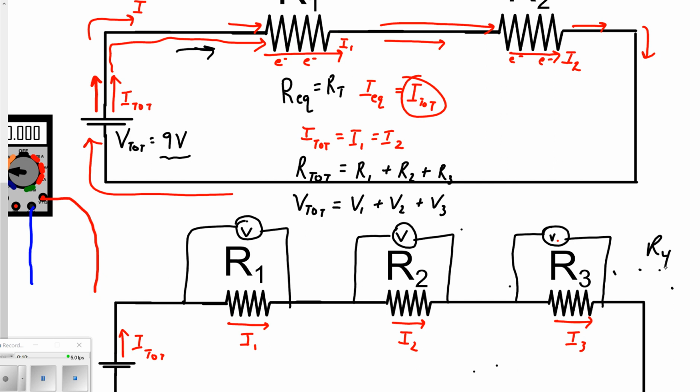And what you would find is this: the biggest resistors would also correspond to the largest potentials. Because if you want to think of it, let's say we had a 10 ohm resistor, a 20 ohm resistor, and let's say the last one was a 30 ohm resistor. Which one of the 3 resistors should be the hardest for this battery to push the electrons through? Well, obviously, the 30 ohm resistor should be the hardest to get the current through, so we would have the greatest potential present over this resistor. And for that matter, it would be the 10 ohm resistor that has the least.